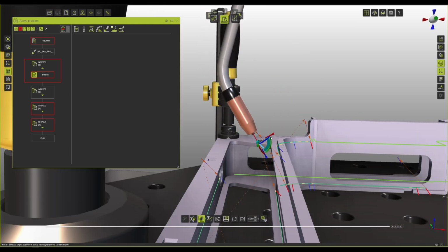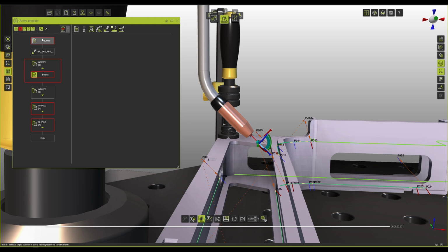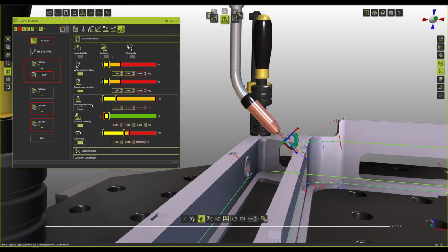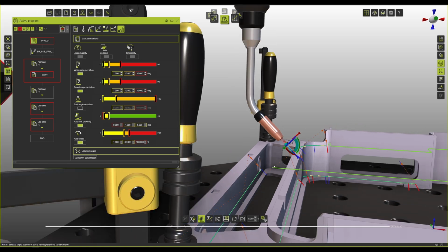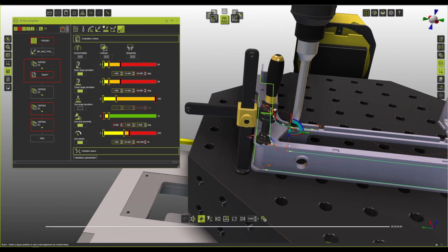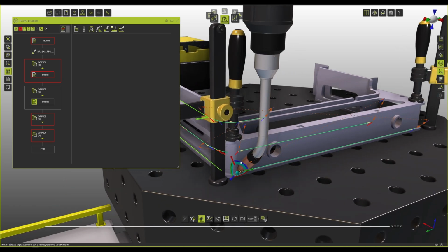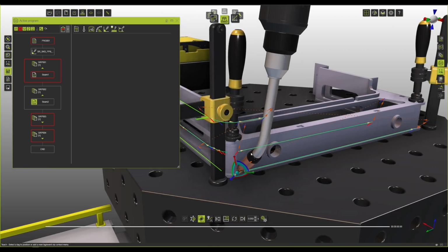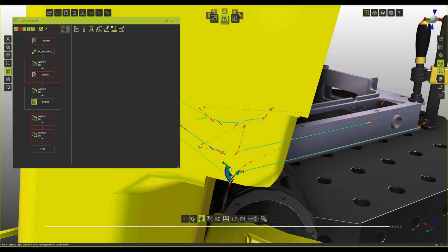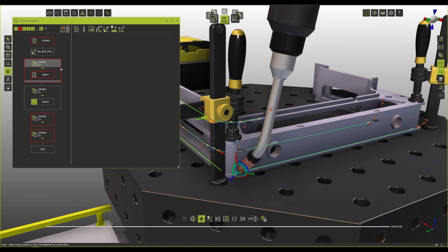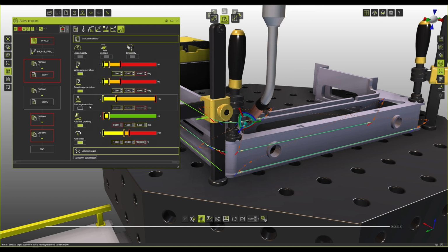The last one is a bit special. This is the tool deviation. That means how the robot is going to rotate around the set axis of the tool. For most single torches, this is pretty much free, because pretty much all 360 degrees are valid solutions for this one. So by default, this one is not evaluated, which means anything here is not taken into account. So you can modify this one as freely as you can, and it is only going to focus on keeping the other two at the lowest amount of overall cost and deviations and transition between points. So everything that we're taking into account.